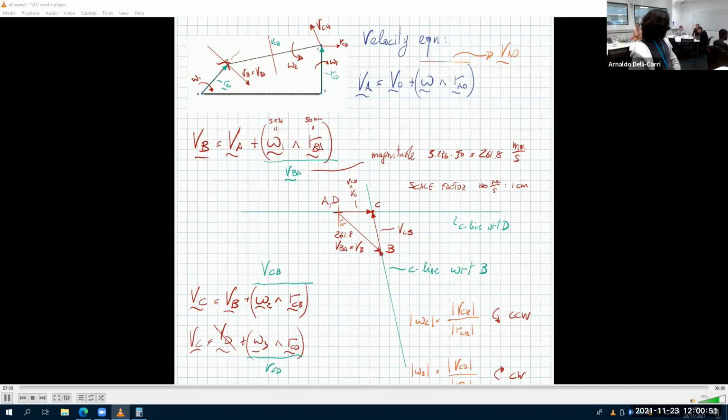Like this. That's BC, going like that. Oh, how come you drew it? I mean, that's C with respect to B, as if B was fixed. Now, B is not fixed. So the absolute velocity of C is to the right. On a fixed observer, C is going to the right. But if you were sitting on B, you would see C moving top left. Okay, that's the idea.